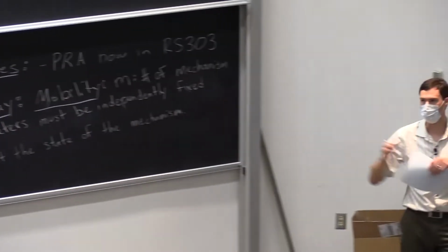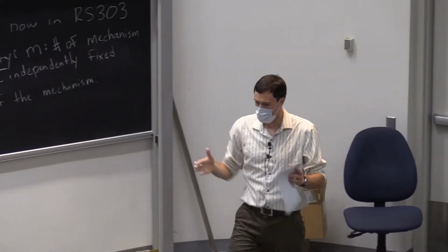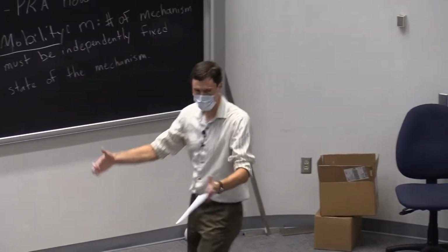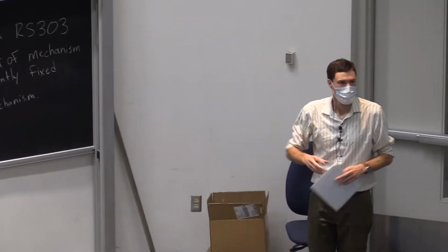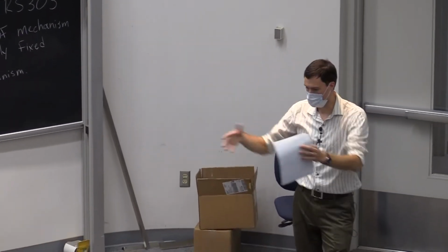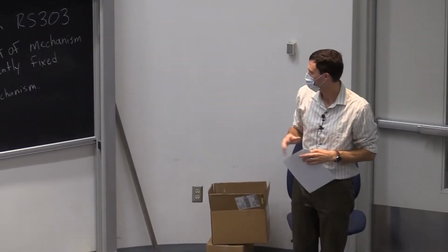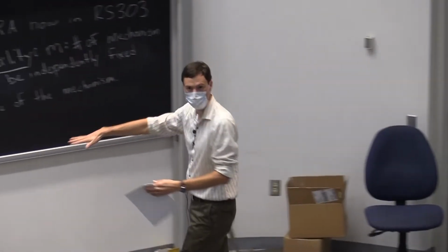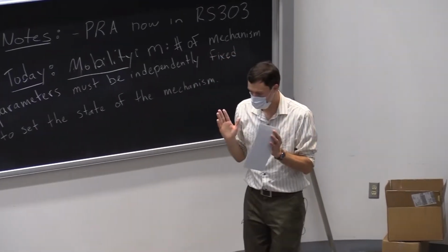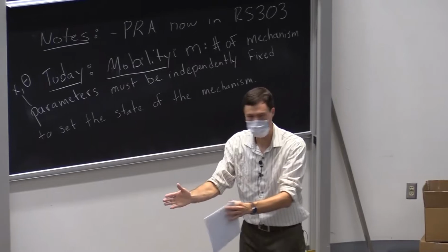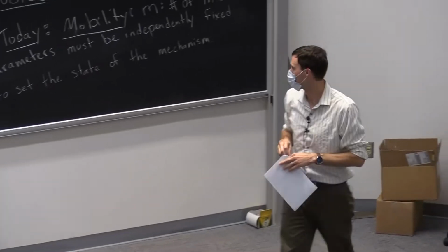So if we have a car going down the road, it has 4 wheels, and thousands of components in it. All I'm talking about right now is the motion forward and turning. So how many mechanism parameters do you need to know? If you're just looking at a car, let's say we set it on the ground, how many parameters would we need to be able to specify? That one's a little bit tricky, actually, because it can move in x and y on the plane of the ground. So that's like 2. Another way of thinking about it is it can move forward and it can turn. So that's like another 2, another way of describing mobility.